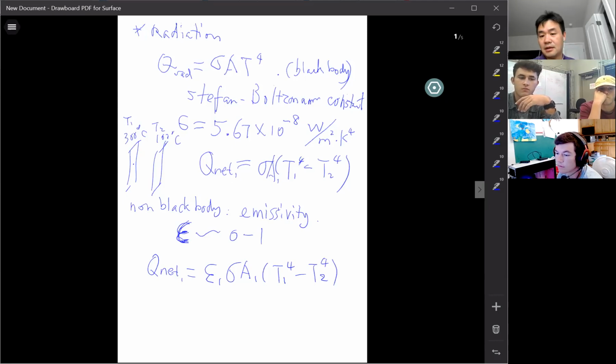What page was this again? Page 663. You asked for the page number, right? And see, it gives you a temperature range, and also an emissivity range in this temperature range. So you need to make some decision, some calculation, maybe linear interpolation. For example, if your temperature is 500 degrees, I would say my emissivity should be 0.029 for this polished brass surface.